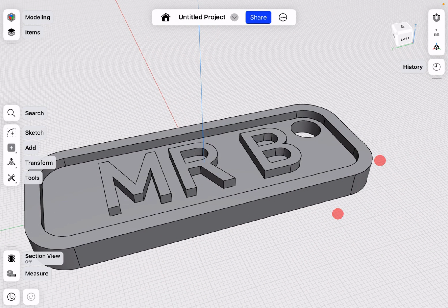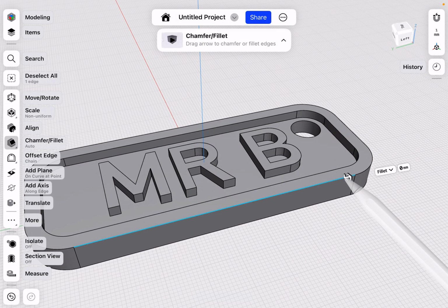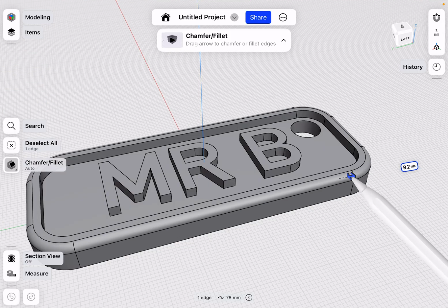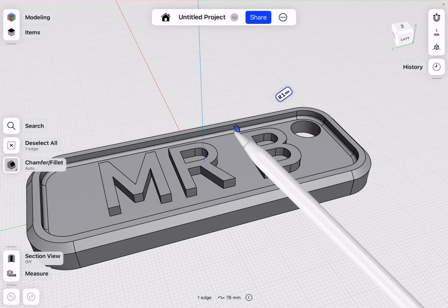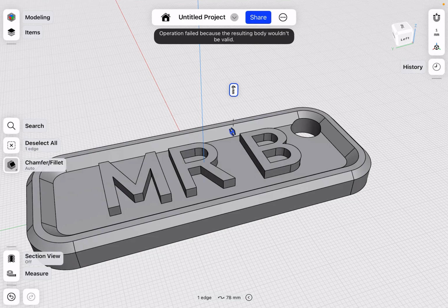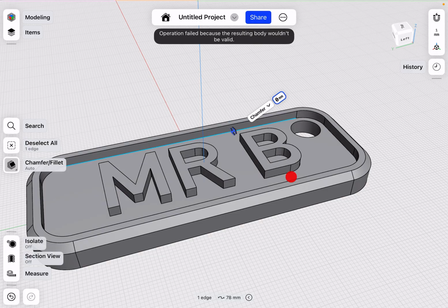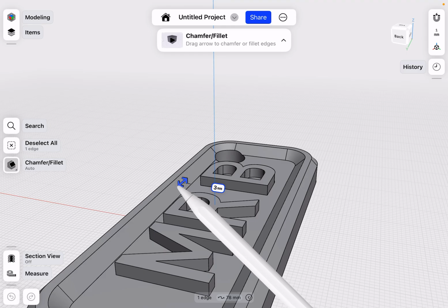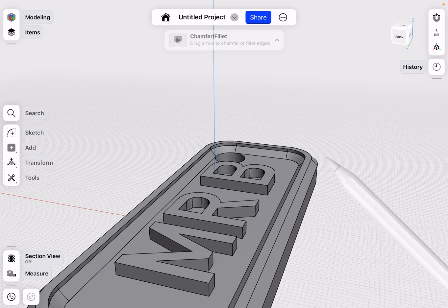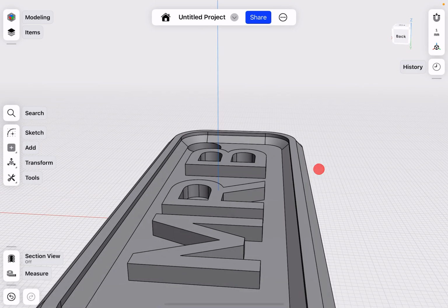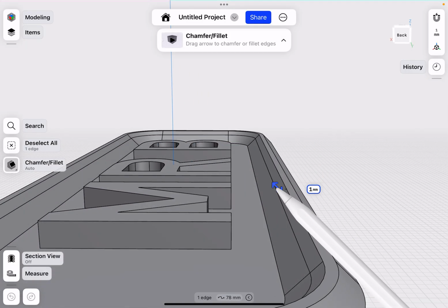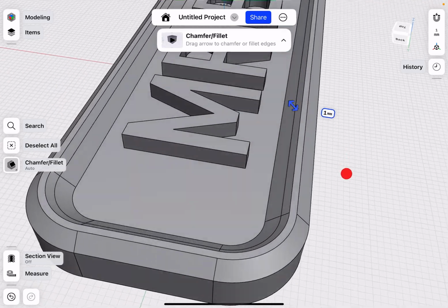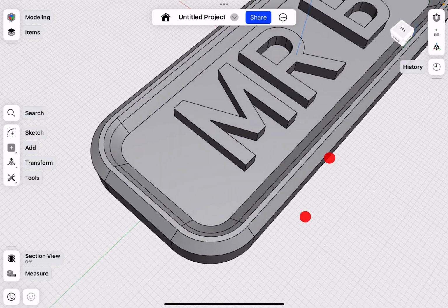There's my basic design. Now what's quite nice to do is, sharp corners generally in design are not very nice. So we can either do a nice fillet going around the edge, or we can do a chamfer. So chamfer being like an angled edge. I can do a chamfer down here as well, or fillet down here. So you see you can do some quite nice. Let's see if that's going to work actually. Can you do that? Very good. And we could also do, just for that little raised lip there, either a fillet or we could join up the chamfers there. So it's like one big chamfer, which could look quite nice.